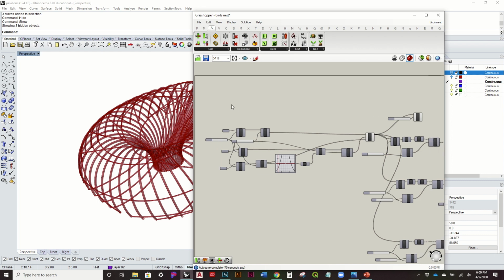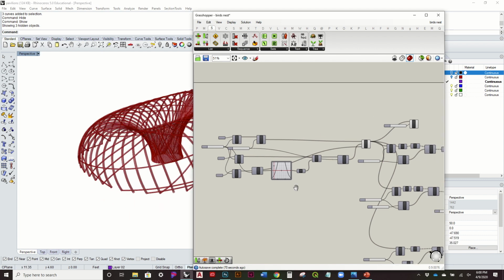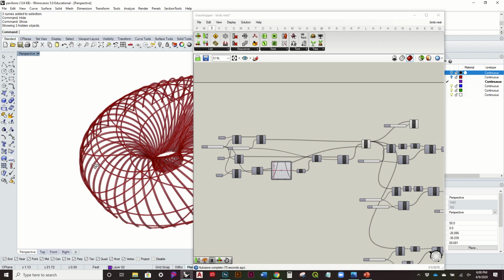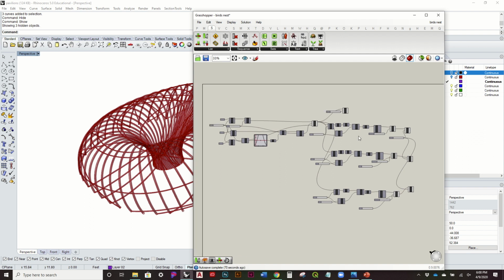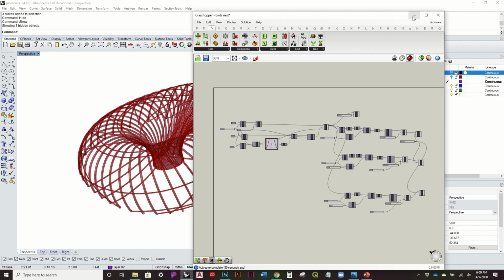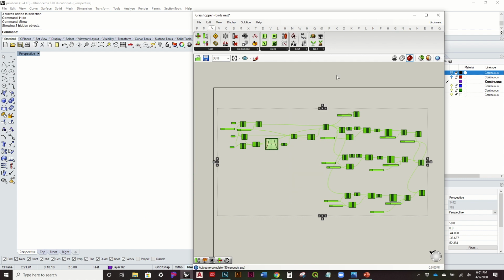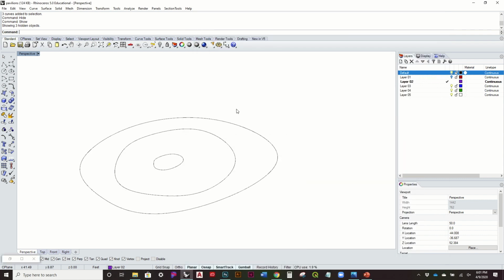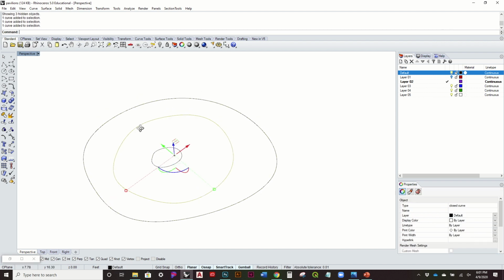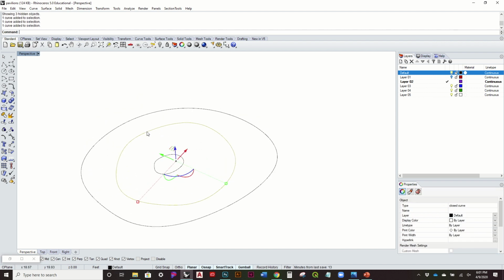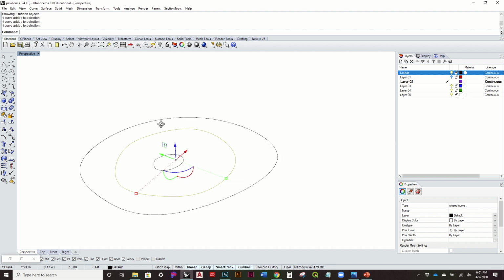So you're basically creating some arcs and then you're starting to do all sorts of cool twisting and connecting of them all. And it's a lot of copy and paste. So you can even see that overall the script's pretty simple. And what you have to actually do in Rhino is also very simple. If I just go ahead and turn this off, what I have is an outer circle, this inner circle, and this middle curve that's going to help us determine those angles.